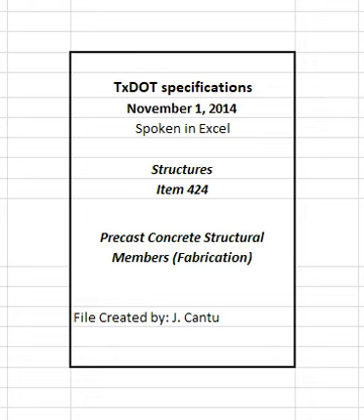Do not allow the air temperature to exceed 160 degrees Fahrenheit for more than one cumulative hour during the entire curing period. Do not allow the air temperature to exceed 170 degrees Fahrenheit at any time during the specified curing period. Arrange the location of the heat discharge into the curing enclosure so temperature variations do not exceed 20 degrees Fahrenheit between any points in the curing enclosure.